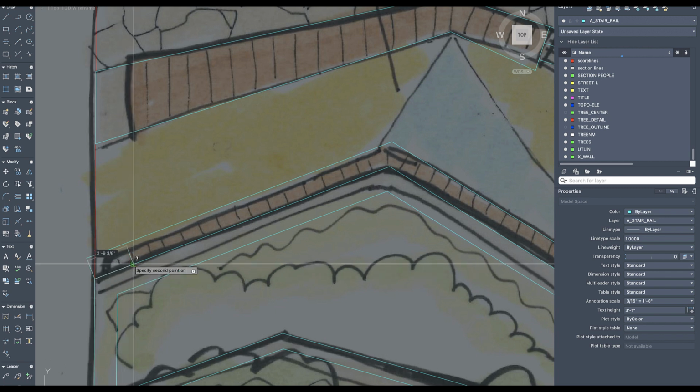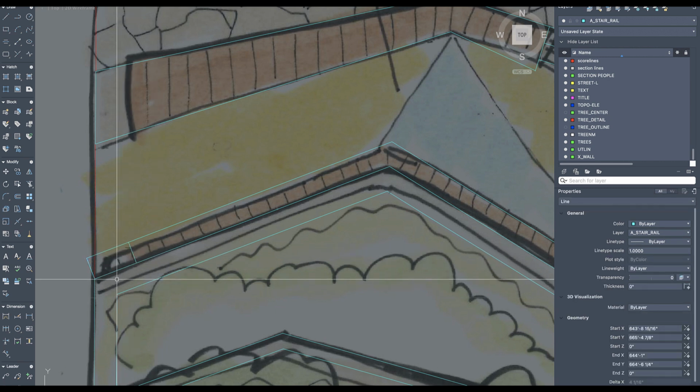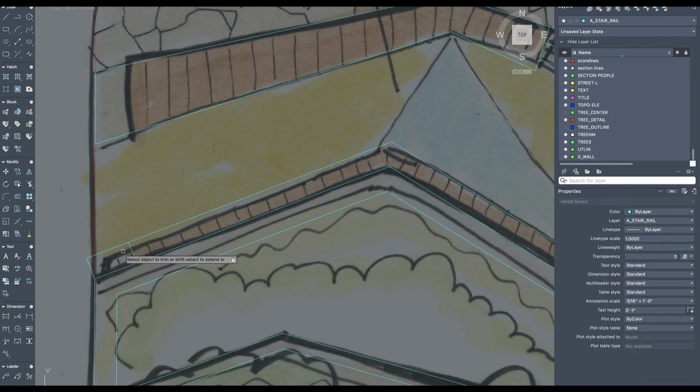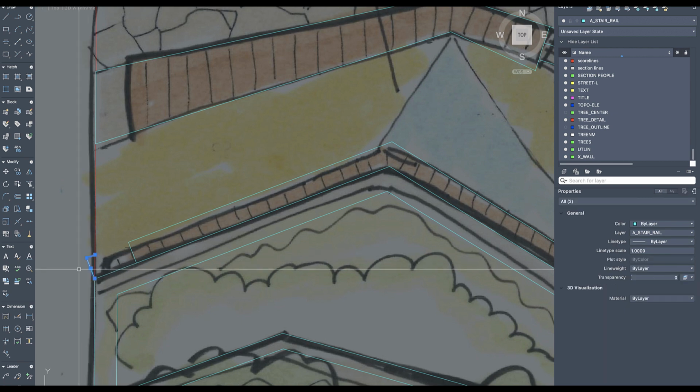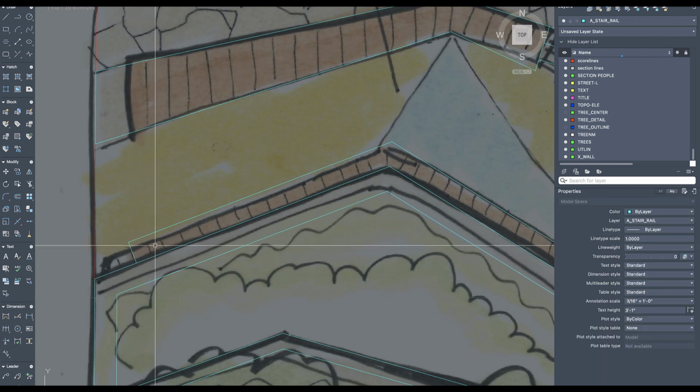Try to avoid just arbitrarily drawing in lines. You can see that the offset that we would end up dimensioning as 2 feet 9 3/8 inch, not a number that we want to do, right? So we want to find roughly what we want that to be by drawing it in, and then what we'll do is we'll offset this a whole number. In this case, 3 feet, so we can dimension that and say exactly 3 feet from that edge is where we want to put our bench coming in.